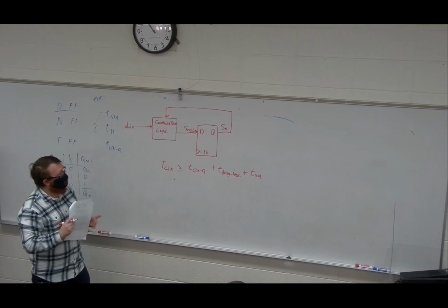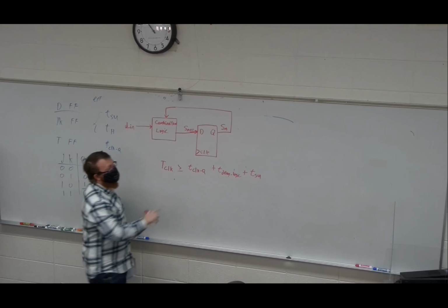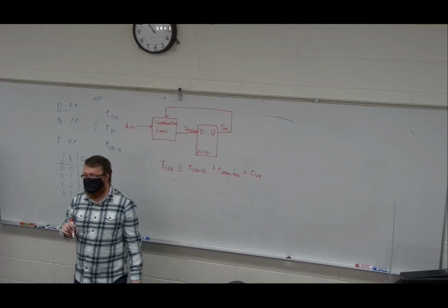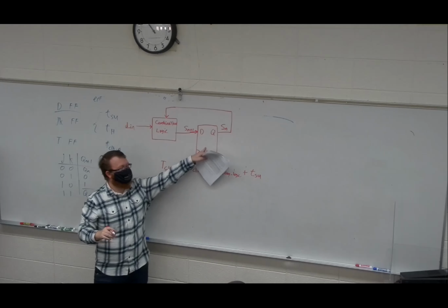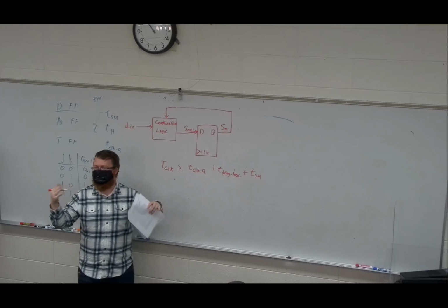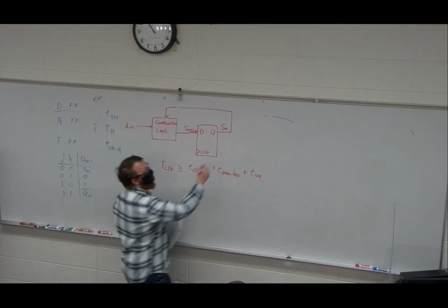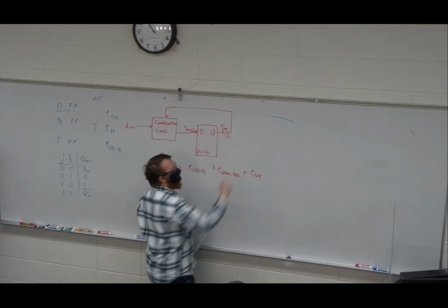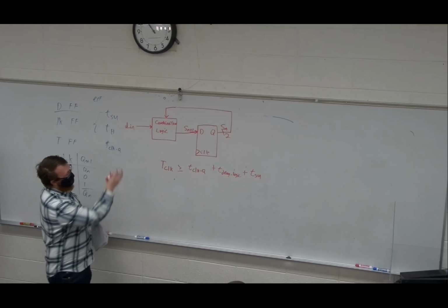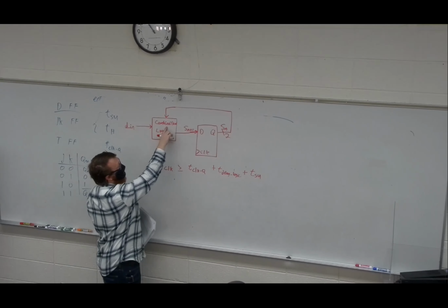Now, the way it works is, let's say we are at a red light. So that means the output here is red, right? We would actually need two of these, right? Because if there are three states, red, green, yellow, then I need 2 bits. Right now I'm only storing 1. But we can remember that we can do this and say now it's 2 bits wide, right? So now I can say the output SN, the current state, is red. That feeds back to here.